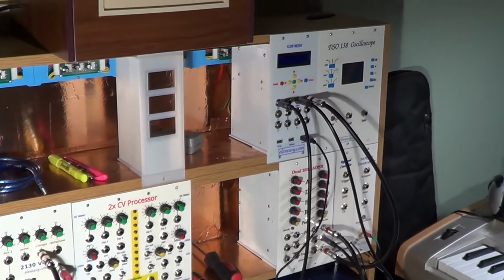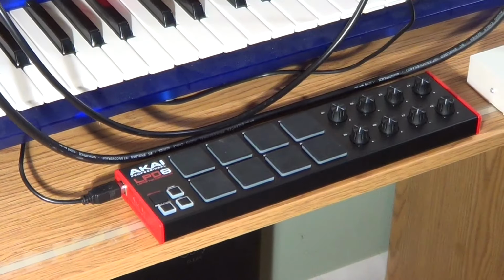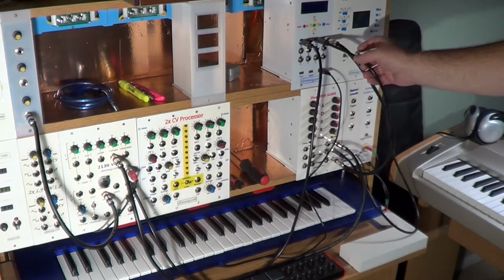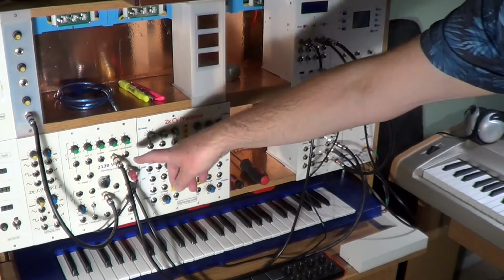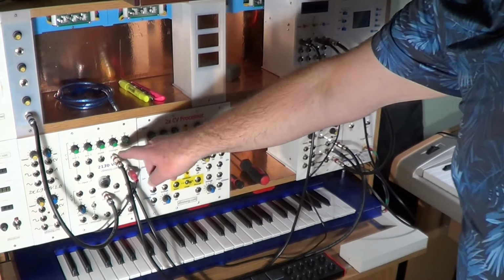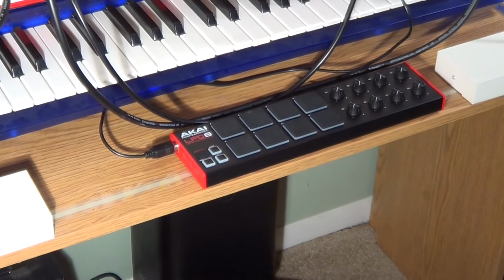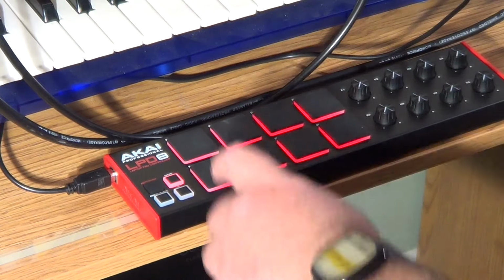I have installed the MIDI module and connected it to the AKAI LPD8, which is right here. And the MIDI module is connected on its own through the VCO, and then there is a gate and trigger signal that go directly to the ADSR module, and the output of the ADSR module goes to the VCA incorporated into the VCO to handle a triangular wave. This way, when I use the pads of the LPD8, I should hear sounds coming out of the VCO, modulated in amplitude through the ADSR. Let's try to do that. And I will concentrate my hands on the LPD8. Let's turn it on. The module is ready, and let's go.